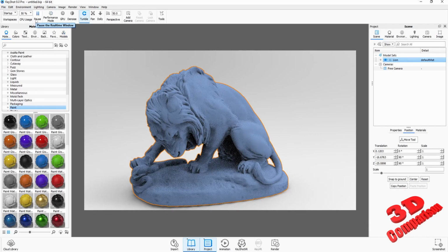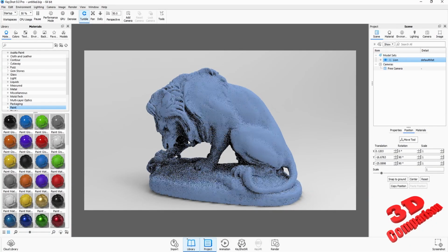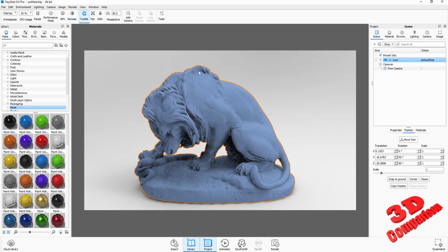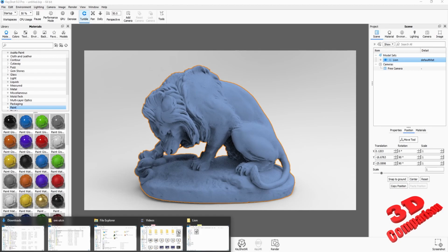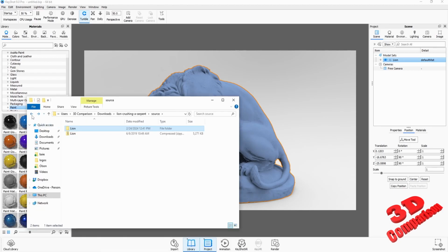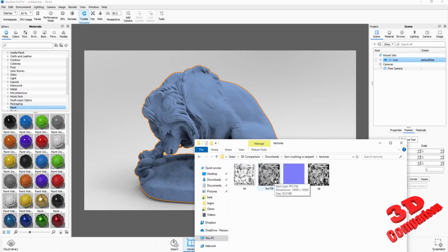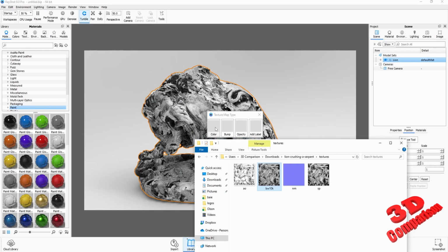Now, since this is set to real-time rendering, every time within Keyshot that you're gonna rotate, you're gonna see that the model will take a little bit of time to stabilize, and all that noise should disappear. Now, if you would to apply the texture that we previously downloaded from that archive, I can go over here to this one, and this will be the JPEG file. I can drag and drop this, position it on the model, and this will go within the color section for this one.